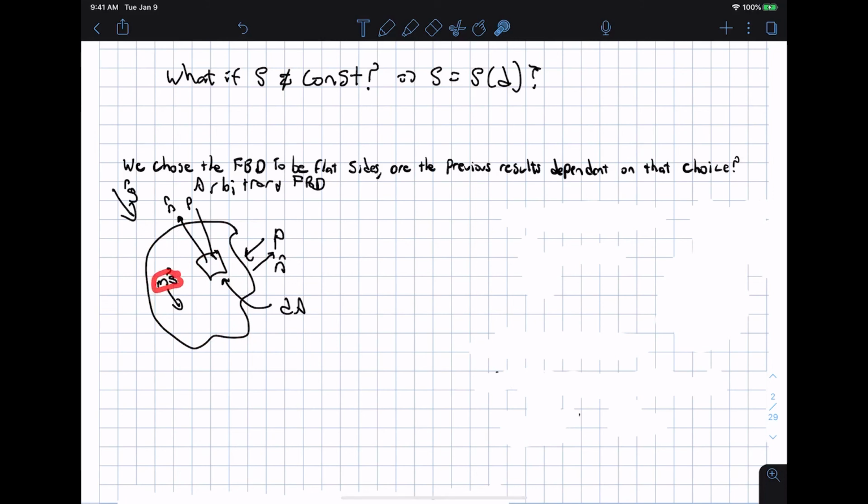And also we'll have a net weight. I have the net weight drawn here as m times g, but in reality, because the density might be different over here than it is over here, what you have to do is consider the weight in a small little differential volume, like that. I'll call that dW, a force acting on that, and that equals rho at that point times the volume, dV, times the gravity vector. To find the net weight, we basically add up all of these differential weights in all of these tiny little volumes.